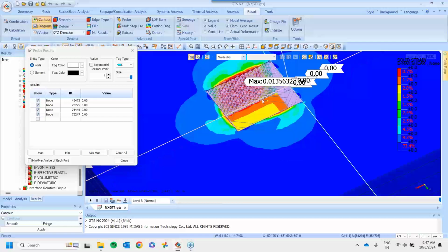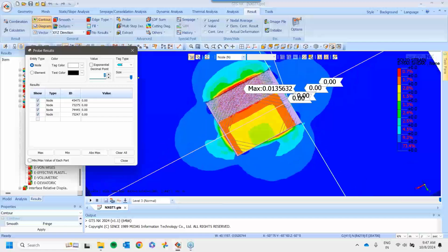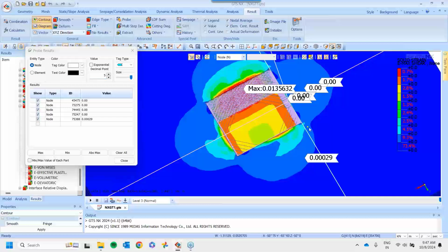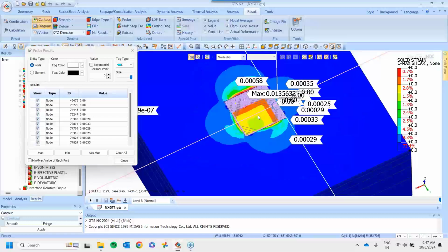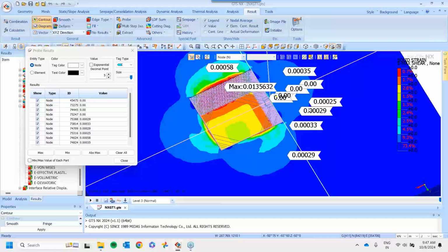You can see the shear strains localization, the value is quite low, which should be the case because the higher it is, the higher is the chance of collapse. Here we are getting around 1% shear zone close to the vicinity, and it is a good thing that there is a retaining wall which is able to restrict the movement of the soil.